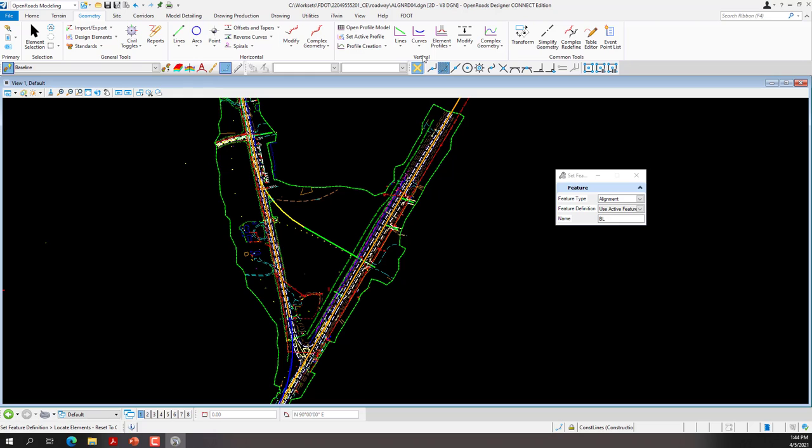Our maximum tangent deflection without curve is 1 degree. The minimum horizontal radius is 694 feet. And the minimum length of the curve will be 675 feet. But our context class that we're going to use to help us design the profile will come from C3 with a max grade table from 210.10.1.